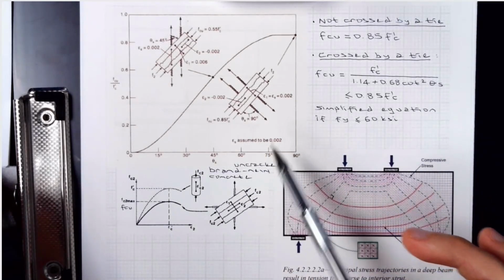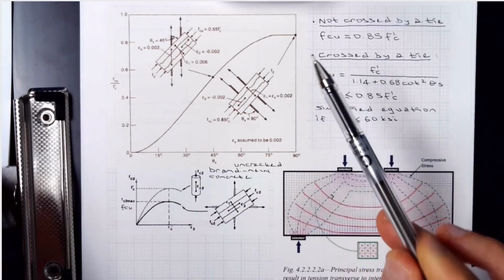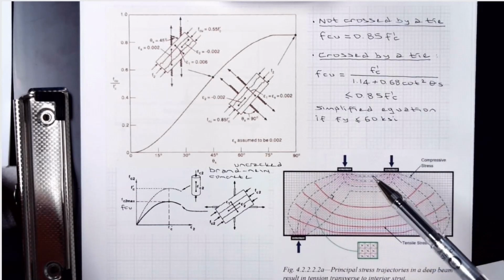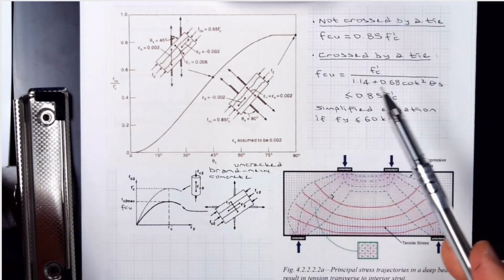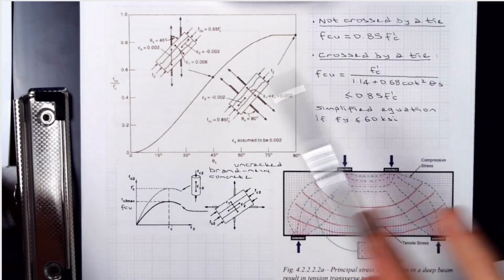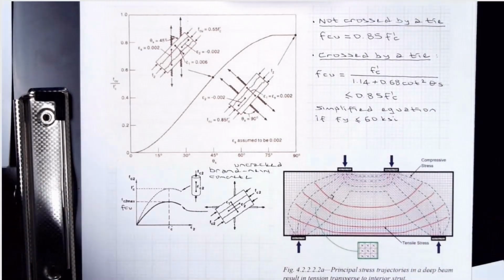For large thetas, the best one is 90 degrees, right, which is the 0.85 situation, which is this one. You have 90 degrees at this location because it's a horizontal strut. Tension would be vertical if there's any tension. So this shows you really nicely the situation. Okay,